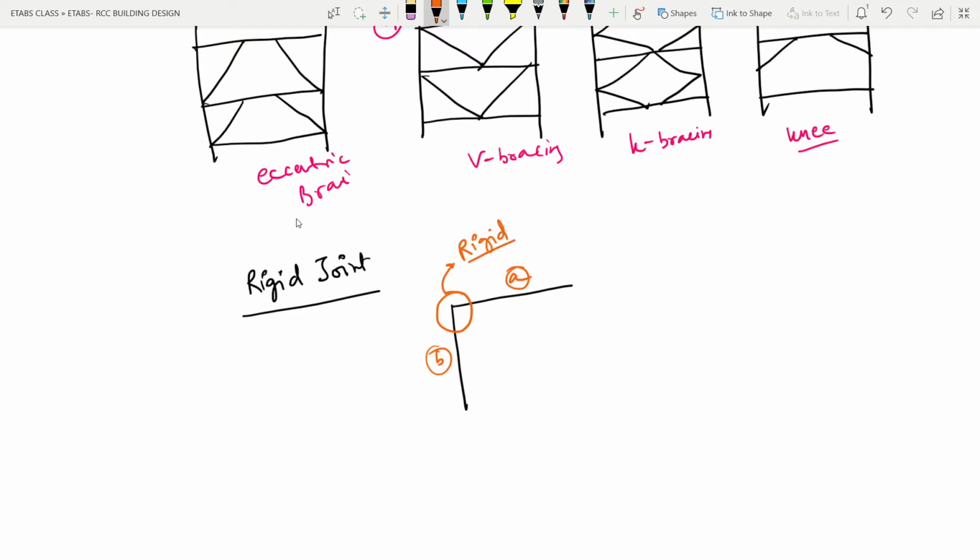Full extent of the force. Here we are giving hinged joints, right? The pin joint. So obviously the moments will be released, or like in steel structures you say moment connection, shear connection. So we do not call those fixed connections or rigid connections, right? So this particular node should be capable, maybe not 100%, but to a very major extent, of transmitting the forces coming to these connected members to the other member.